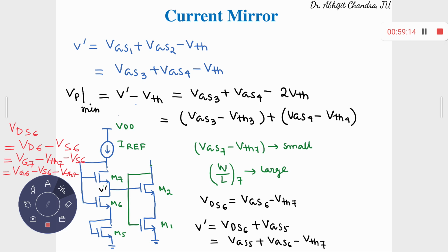So this circuit is much more stable, accurate, and has higher swing. But nothing is obtained free of cost. It comes at the cost of a larger number of MOS devices, so you have more power loss.